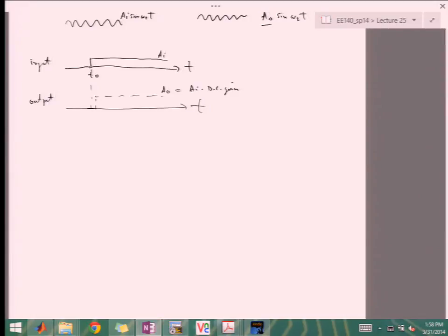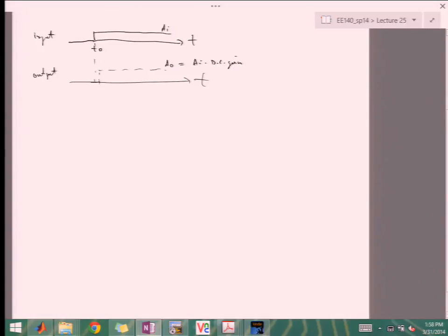Okay. Assume a scenario. If it's overdamped, like a single pole or two pole overdamped, it will be a dominant exponential that gets it to the goal. And as you start critically damping it and underdamping it, it will become faster to respond, but with a little bit of peaking.